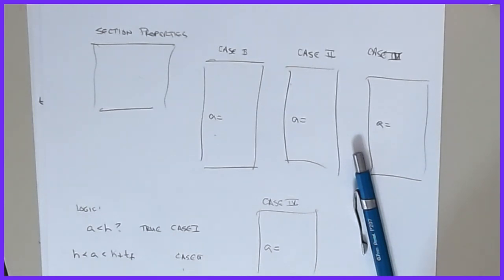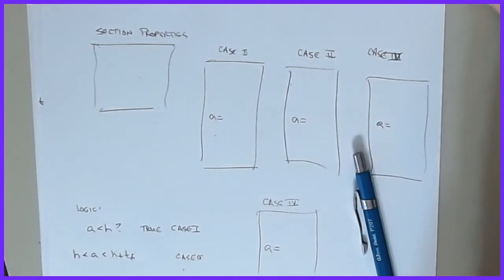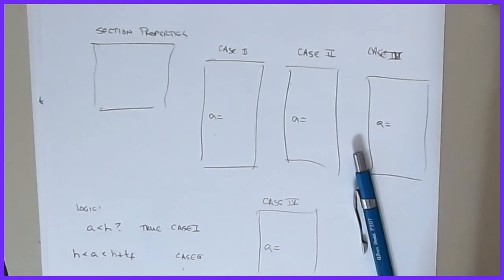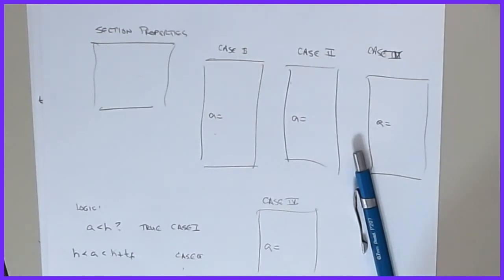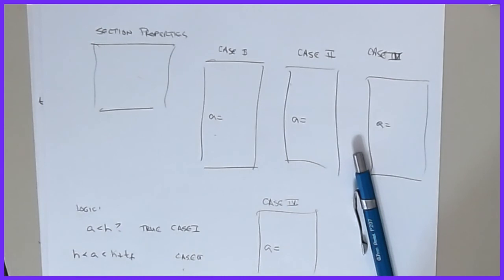All you're doing is the blocks look exactly the same, with the exception that in case 2, now the plastic neutral axis is down in the top flange of your beam, right? So now I've got a C sub C. I have a CFT that's on here, okay? And then the one thing I had to do is split this guy. So this part right here changes a little bit from what I had over here. Does that make sense? Yeah. Yep.